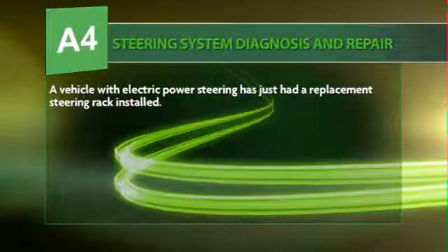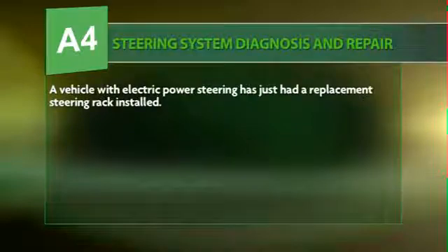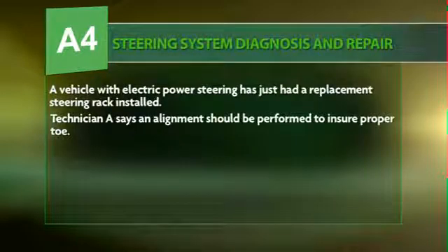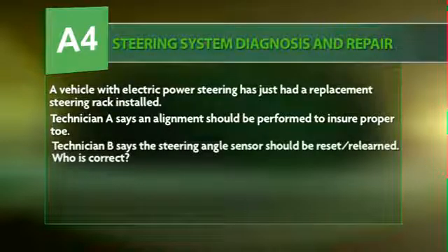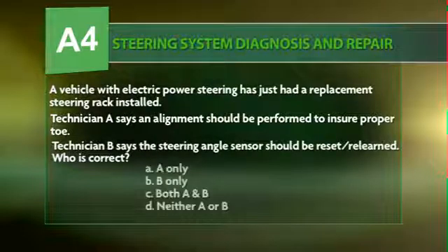And here's how the question might read on your test. A vehicle with electric power steering has just had a replacement rack installed. Technician A says that an alignment should be performed to ensure proper toe. Technician B says the steering angle sensor should be reset or relearned. Who is correct? Well, before we go any further trying to answer this question, let's dissect it a little bit